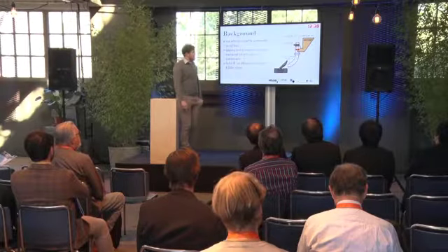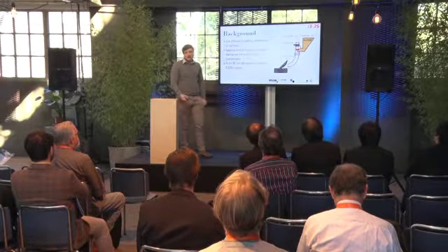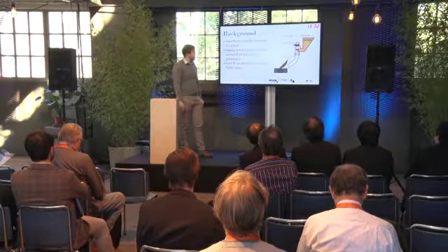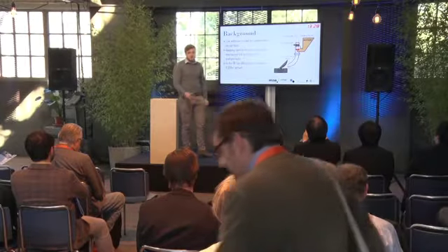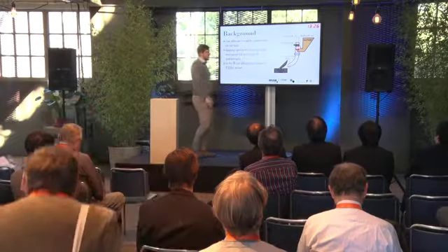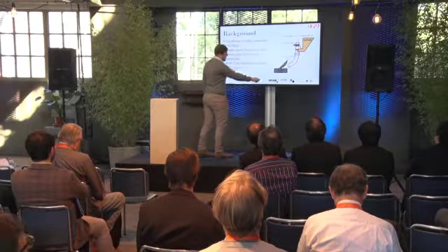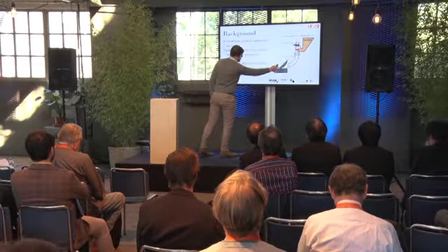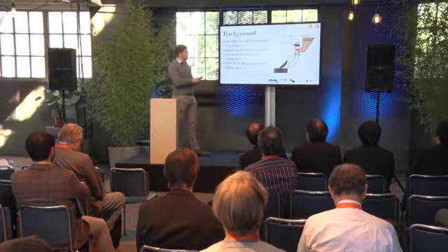Right, so for those of you who don't know what sanding is, when there is low adhesion on the rail, such as leaves and wet rail, as we've had a lot of this past couple of days, you can use sand to try and boost back the adhesion again. So it's usually a train-borne system, such as this beautiful diagram here shows. Sand comes out of this hose and into the contact here, possibly providing some sort of mechanical link and